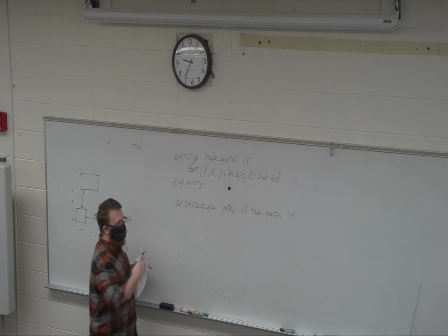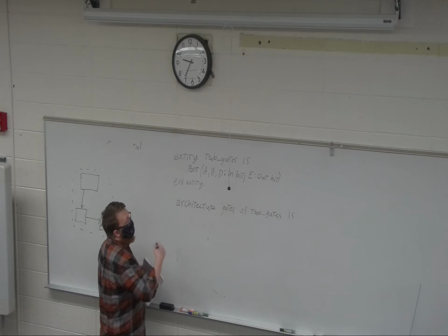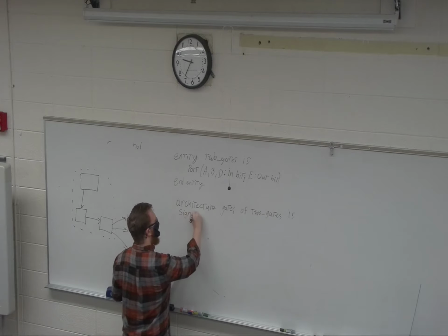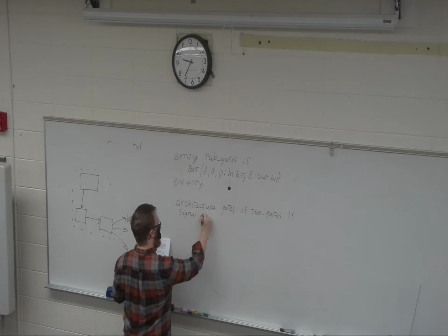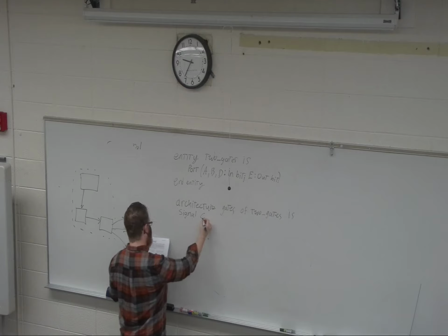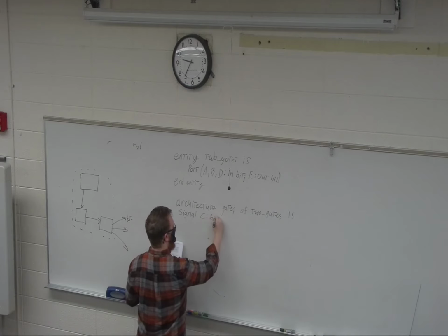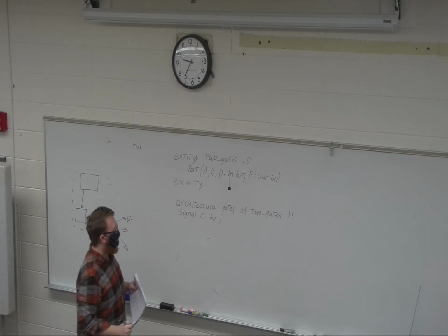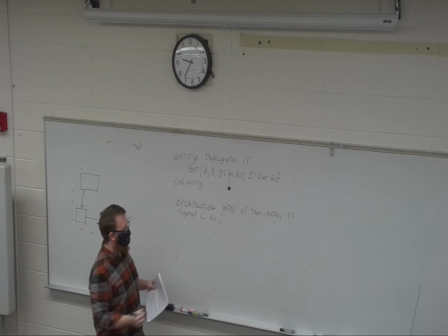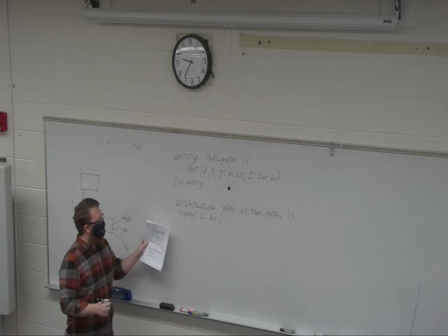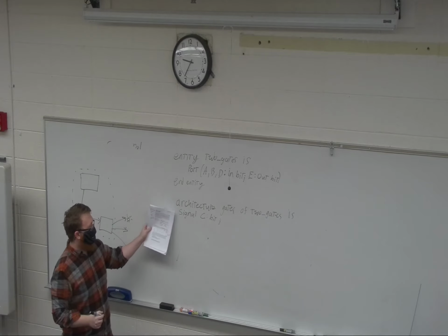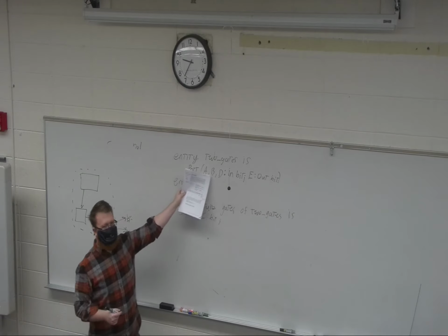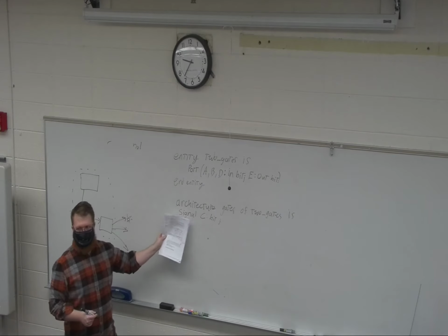But before we go into writing the logic expressions, I know there's going to be an issue because internal to it, there is a signal C, right? And that is a bit. My semicolons look like J's, and I'd really like to apologize for that. So you have architecture. You're defining the signal bit because it's not one of the ports. So anything that isn't one of the ports needs to be defined inside the architecture.